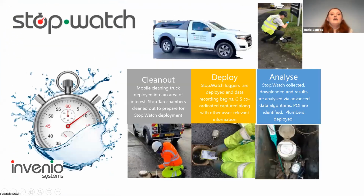Thank you. So Invenio Systems started about 5.5, 6 years ago. It came about by the directors having the idea to use temperature instead of the traditional acoustic methods for leakage detection. It works under the principle that you have the temperature of the water in the main and the temperature in the surrounding ground, and every time there is a use event, you pour water through that. So we started off with some dumb loggers that we deployed to customer stop taps, and we could do various approaches, from a blanket approach to an area to individual targeted properties.